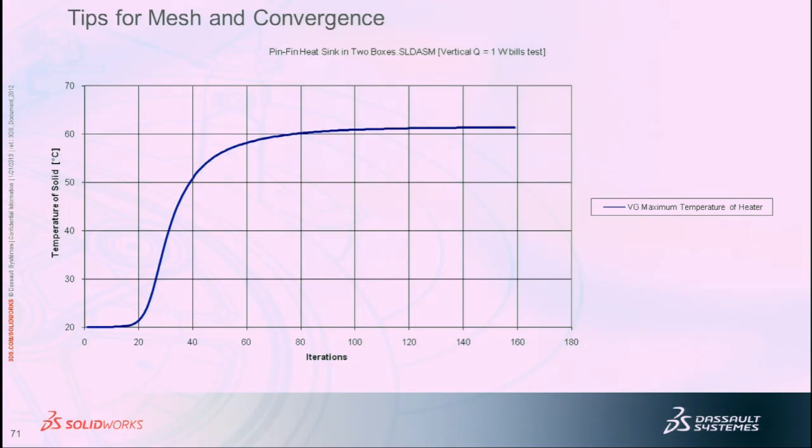It's too costly. But normally downstream, you want to make it 10 diameters. Above and below, it's 3 to 5 diameters, and maybe a couple of diameters in front of the vehicle.